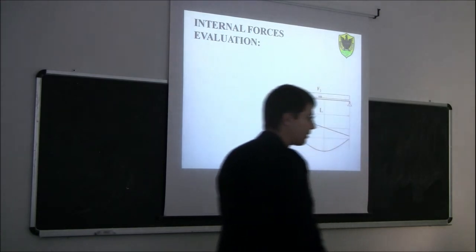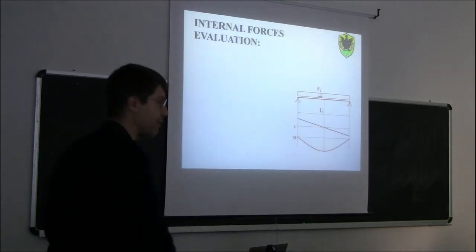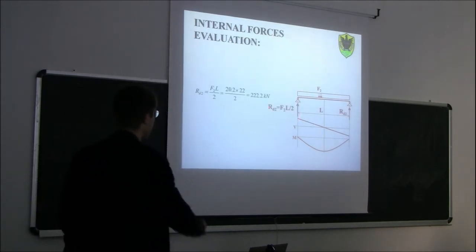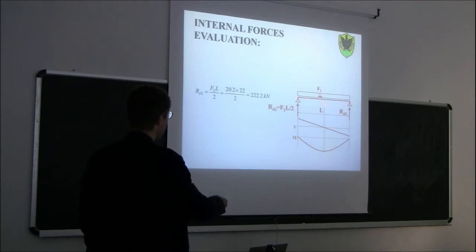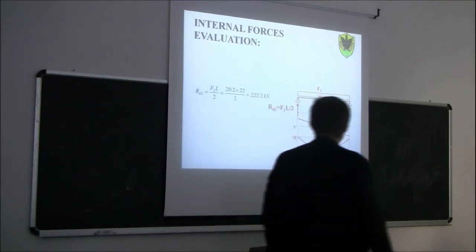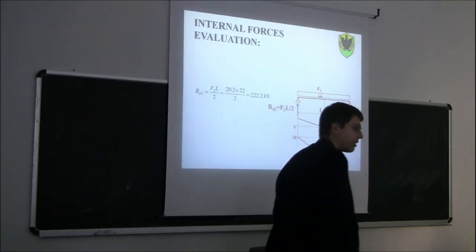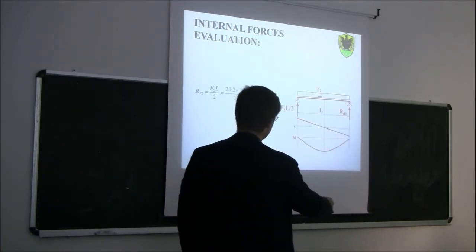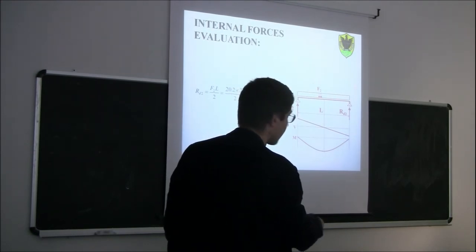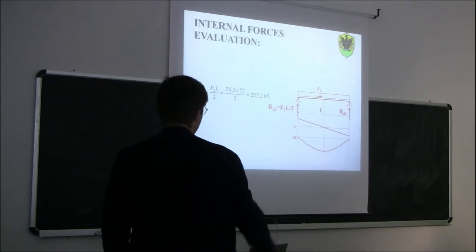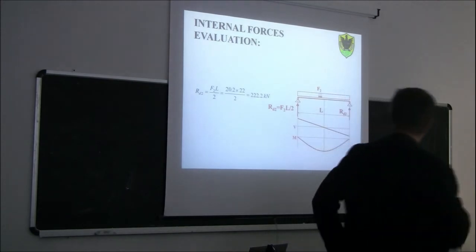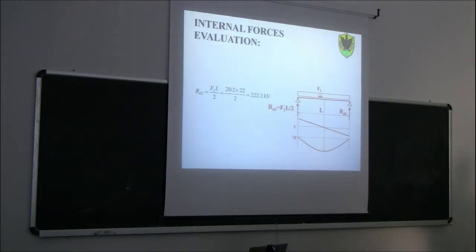All of you probably know by heart the solution of this, not even needed to write the equation. We know that the restraint reaction is basically half of the resultant of the load, so F2 times L divided by 2. This is the restraint reaction, which gives us also the maximum shear over the support. The diagram here is linear, because as you remember, the shear diagram is the integral of the load diagram. Or, if you want, the load diagram is the first derivative of the shear diagram. And then we can calculate the bending moment diagram, which is a parabolic curve.